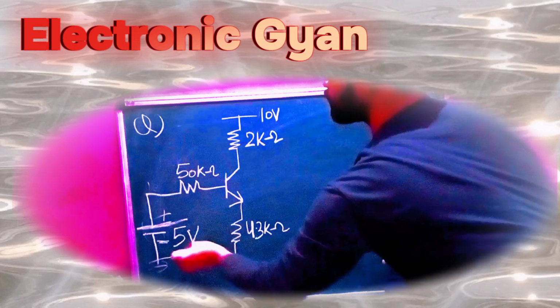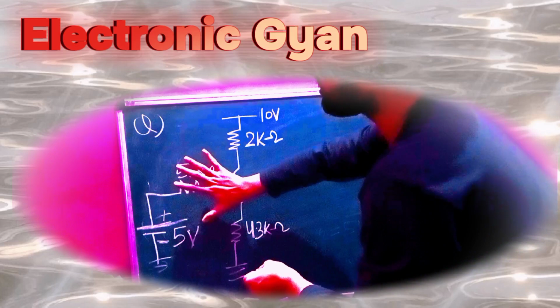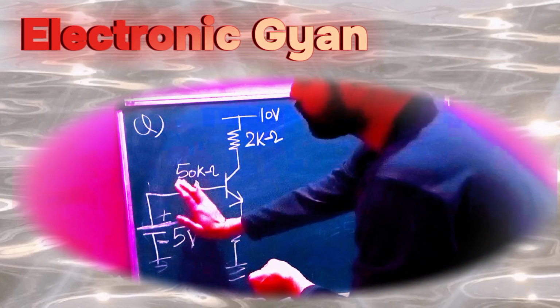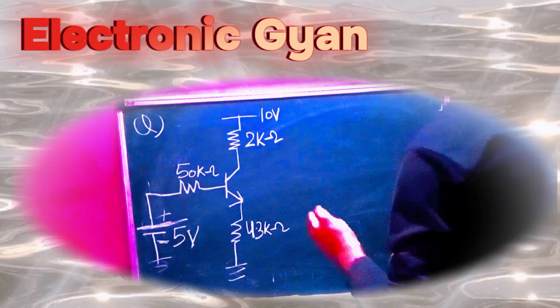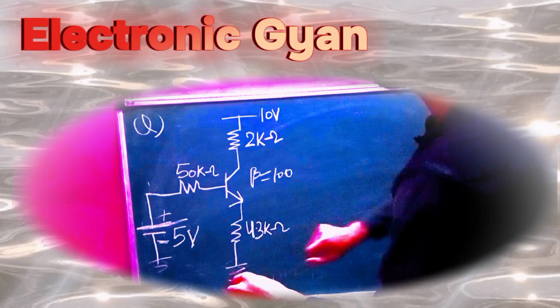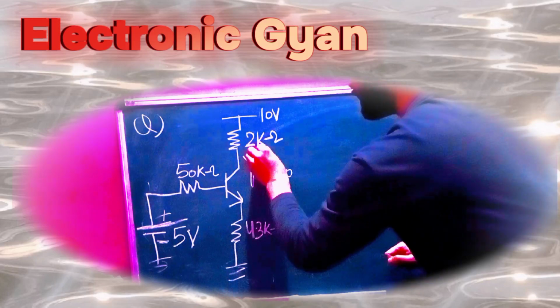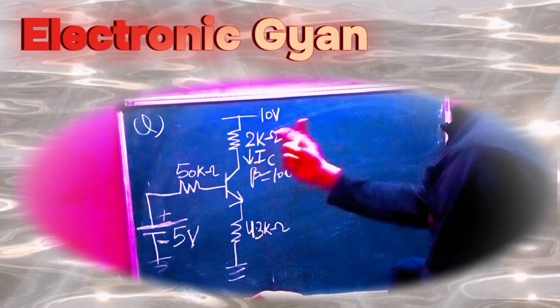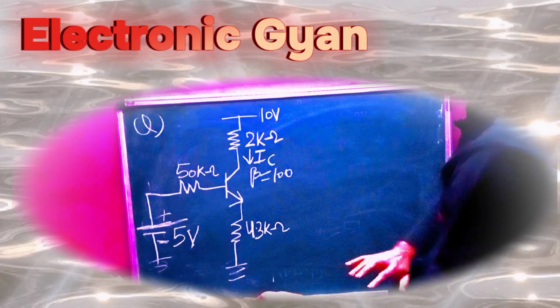Now we have converted the bias side at the base terminal; we have applied the Thevenin equivalent. Beta is given as 100, and here we are going to calculate the collector current. This is our main motive of doing this DC analysis: we want the DC collector current.